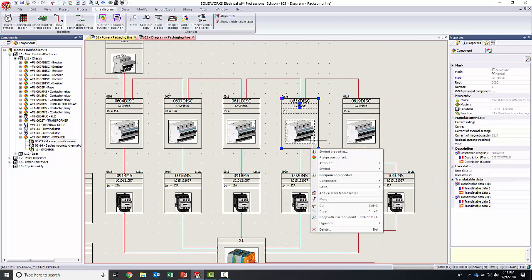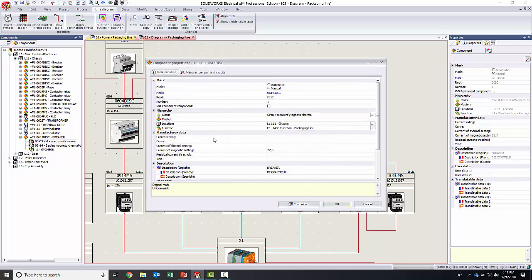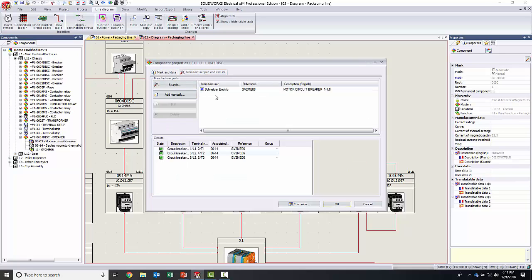If I am looking here, this disconnect, the component itself is the entire operation of this device, whether it be a manufacturer's part, say a Schneider Electric disconnect, but think about that Schneider Electric disconnect. If it's a disconnect, and maybe it's a main disconnect, you've probably got a threaded rod, you probably have a bracket. On the outside of the panel, you've got the handle switch, and those are all extra parts you have to purchase to get that operation to work, you can add all of those parts right here.